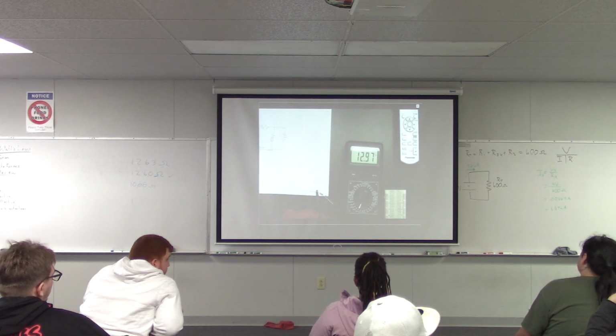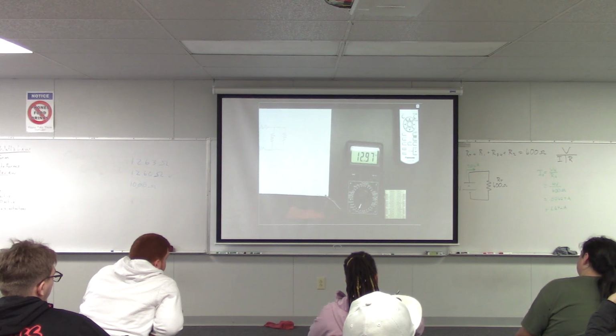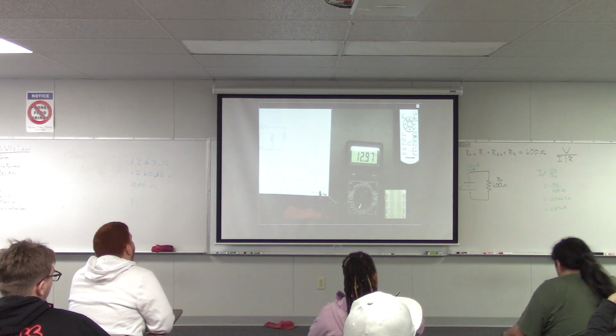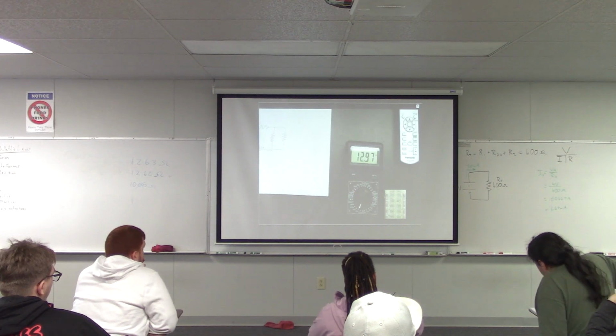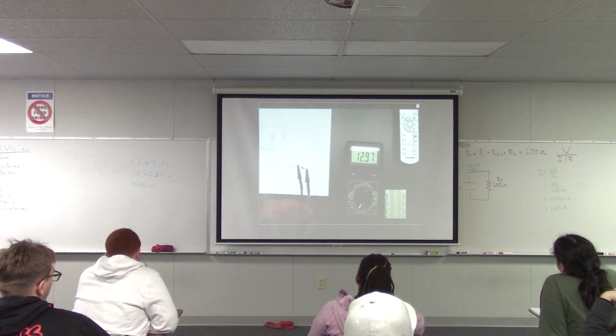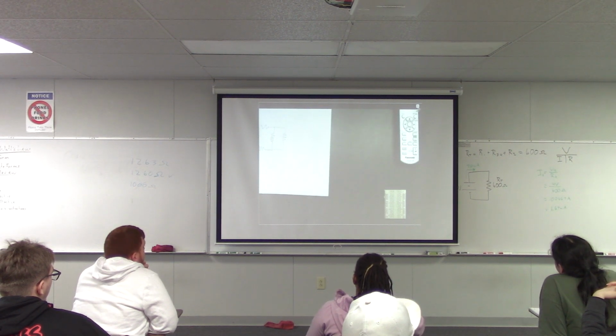Okay. So first of all, measure all 4 of your resistors. Make sure that the values are what you think, and you can write down their actual resistance values too. So rather than just calling this a 13 kilo ohm resistor, you could write down 12.97 kilo ohms. And the more precise you are in writing down the actual values, the closer your math will be to your measured values.